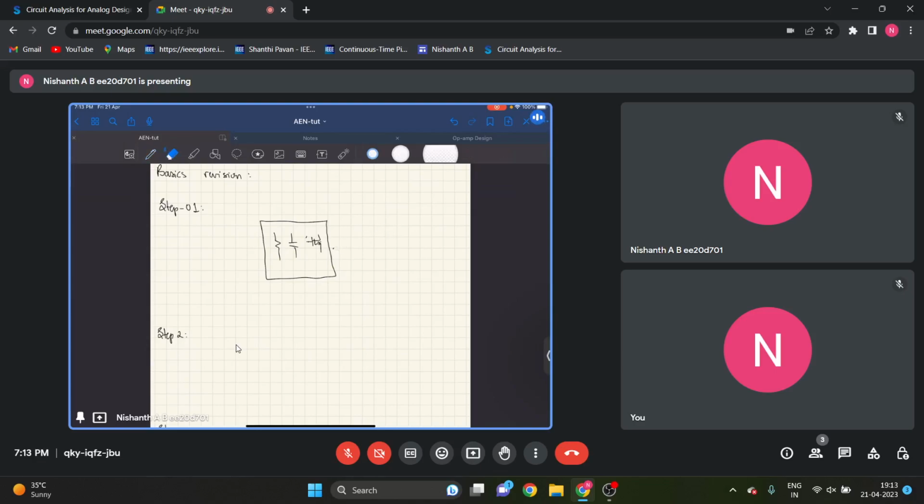But unlike that case, what we basically have to do, if you assume weak nonlinearity, is, first step, assume the entire circuit is linear. Okay. Now, once you assume that, you find all the node equations.